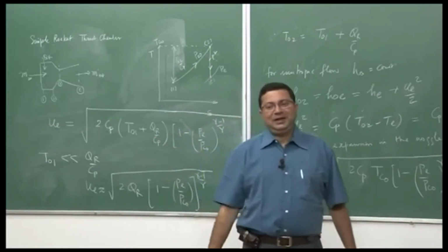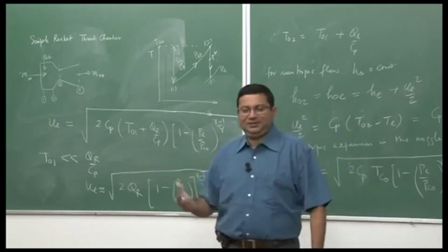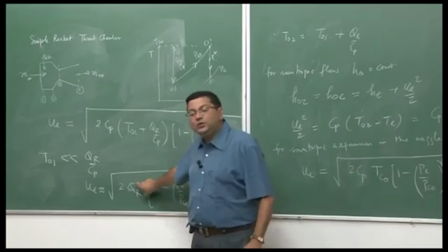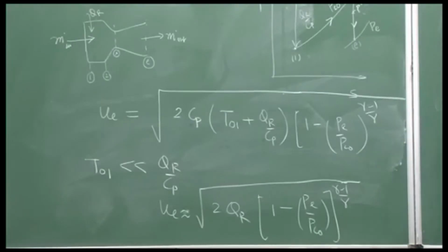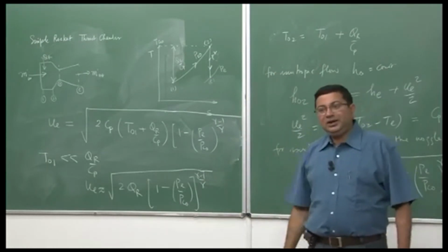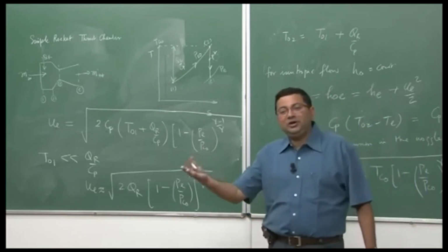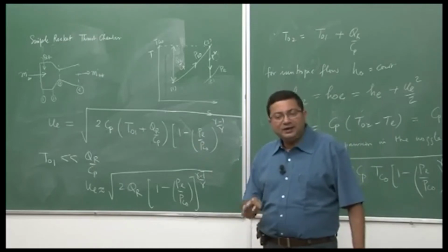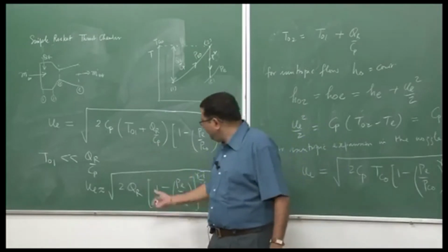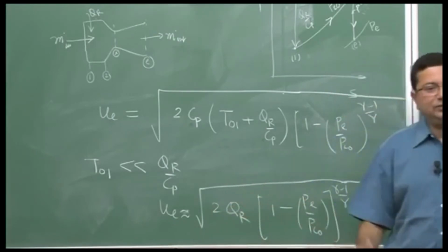Here we are considering that the entire available chemical energy is being converted to thermal energy or heat, right. So, we are assuming that the entire Qr is released, that is why we are eliminating T naught, because then Tc naught becomes a function of the total heating value. In reality, it may not happen. There is something called combustion efficiency; all the heat energy may not be released. In that case, the temperature comes into the picture, or what we do is we say that 90% energy is released. So, we multiply it with the combustion efficiency and then accordingly we can adjust to the requirement.